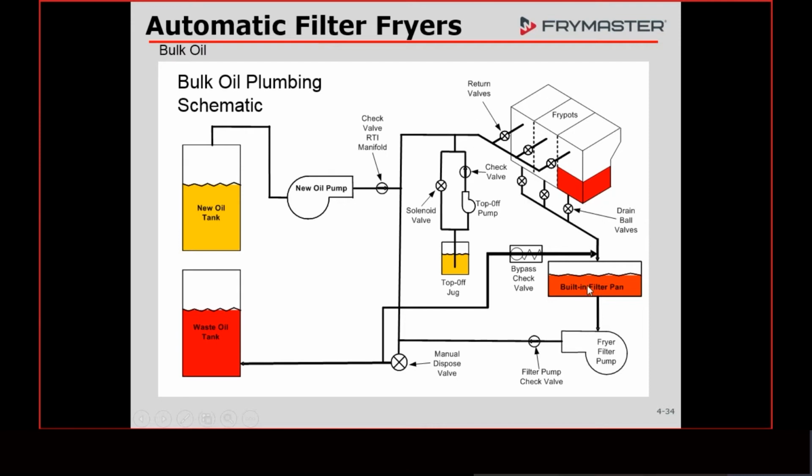So if we're filtering one of these fryers, and this used to happen in the past, we had all different kinds of linkage that would attach to a handle that you would put your hand on and open and close the return valves. We had push-pull cables, we had rods, we had all kinds of different stuff that we would use to open these valves and turn on the pump and motor using a micro switch. Well, they would wear out over time. And when they wore out, sometimes these valves wouldn't close all the way.